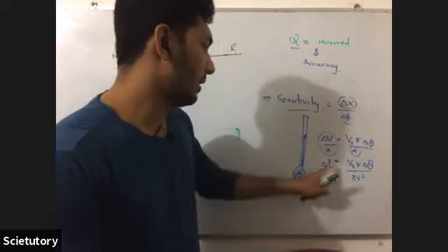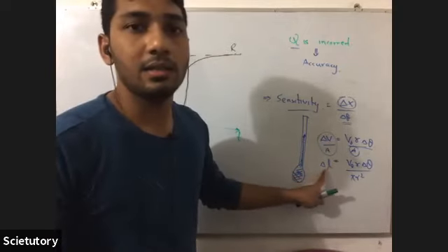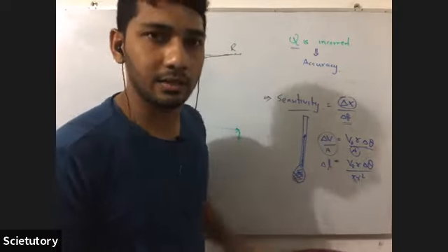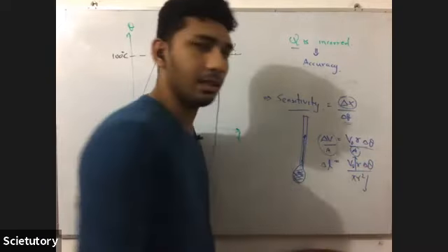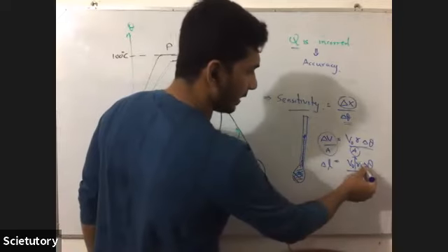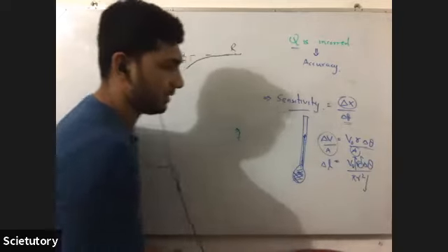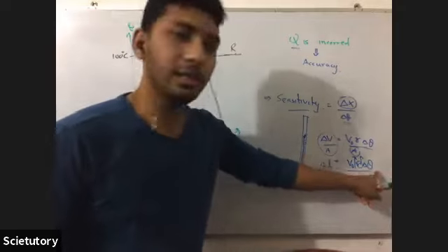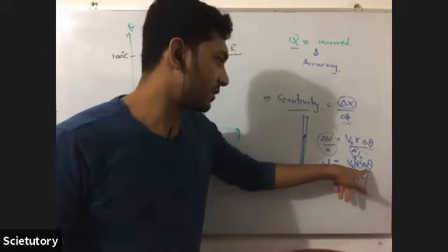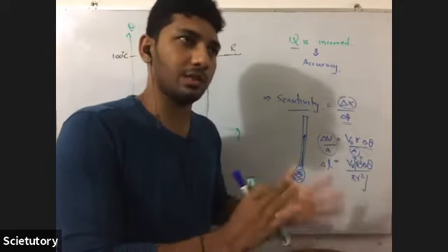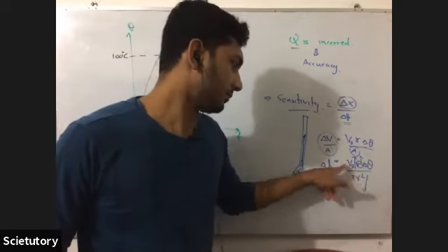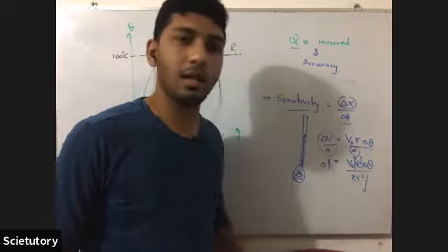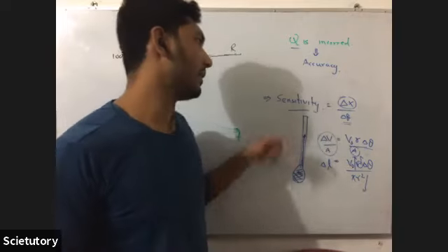To increase the change in the length of the thermometer, you should reduce the radius. You may increase the volume. You may select a liquid with higher expansivity for unit temperature. Expansivity is usually the same because we use the same kind of thermometric liquids. So V naught and r are the factors that determine the sensitivity.